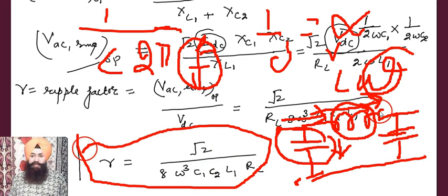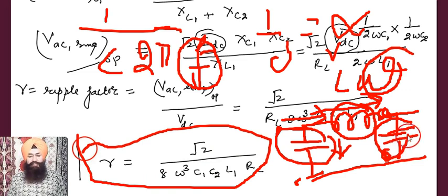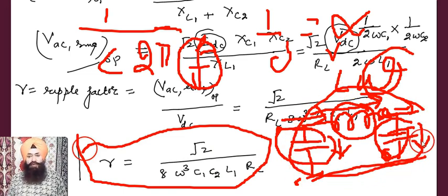But even then, if some component of AC reaches the second capacitor, we again have a capacitor. It again allows the high frequencies to be grounded and the DC to appear across the load. In this way, the pi filter circuit works.